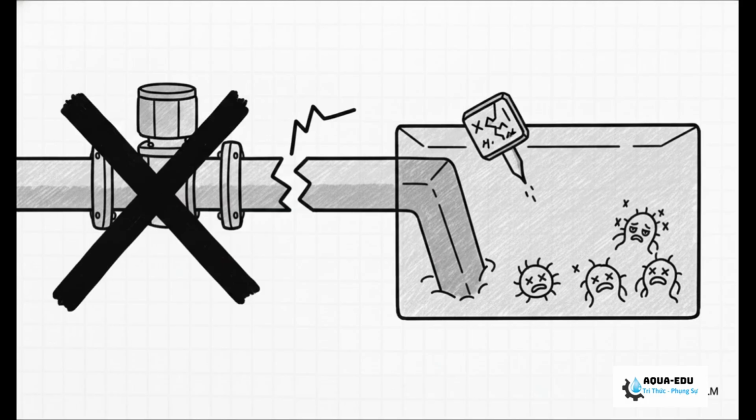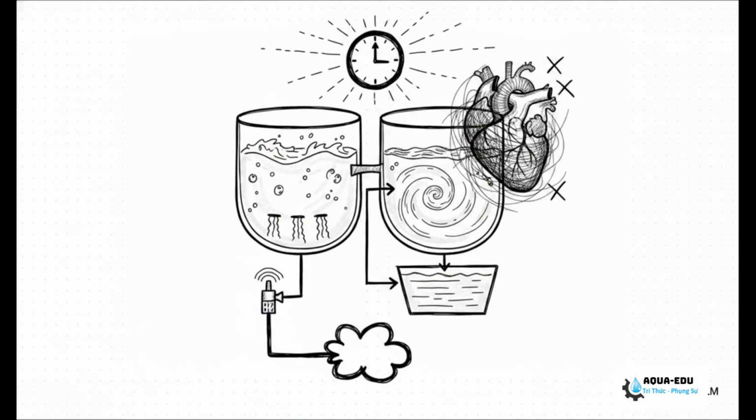Finally, look really closely at your return-activated sludge, or RAS. If your RAS flow stays abnormally fixed because the mixed liquor suspended solid signal is dead, you are rapidly losing control of your biomass inventory, and that is bad news. These active aeration basins and sludge return systems rely completely on accurate, minute-by-minute, real-time data to do their jobs. If you're blindly returning sludge without knowing the actual MLSS concentration, you risk literally suffocating the biological heart of the whole plant.